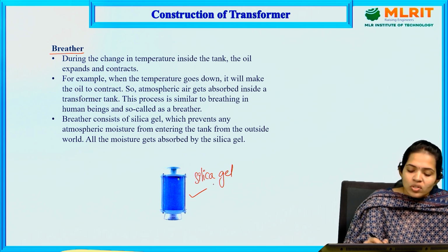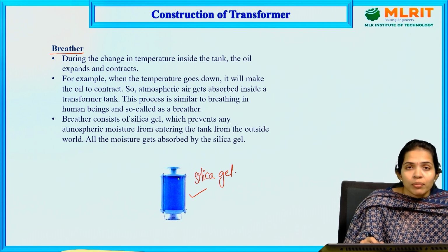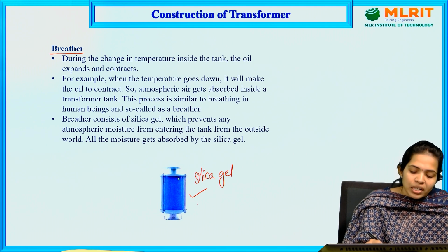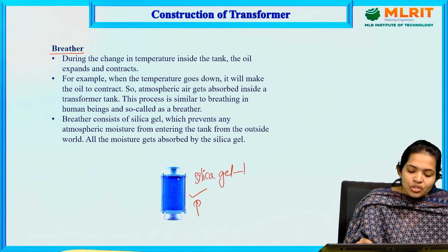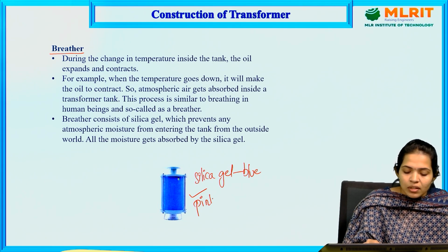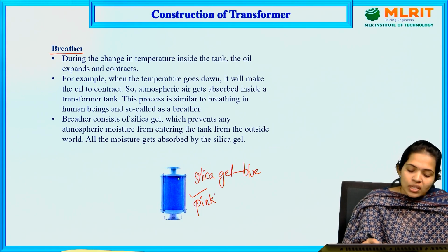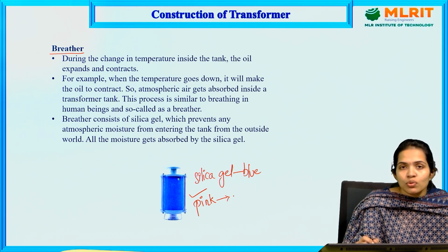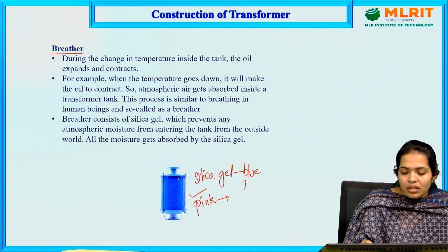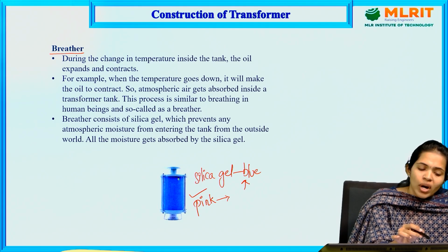This silica gel is initially blue in color. It turns pink when it absorbs moisture from the external environment. The silica gel which has turned pink has to be replaced with new silica gel, which is again blue in color. So what happens in the breather?